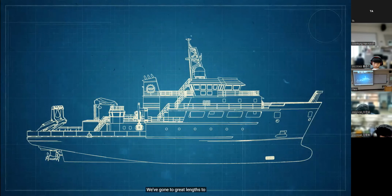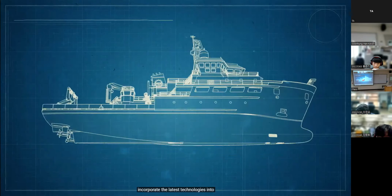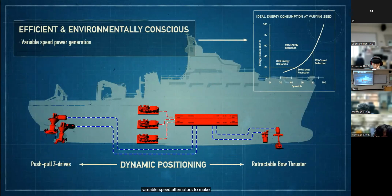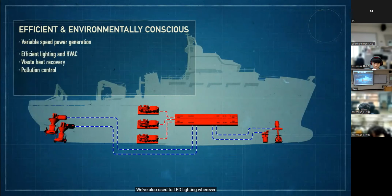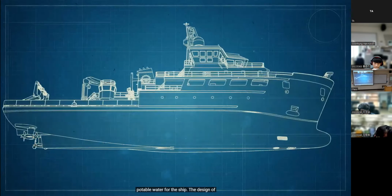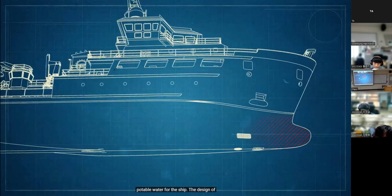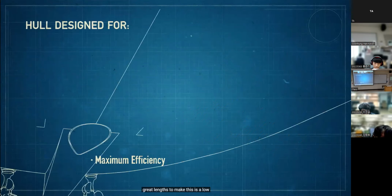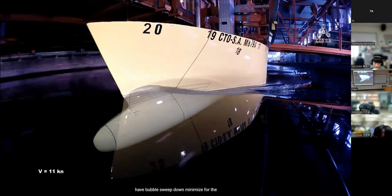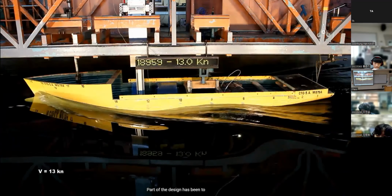When we were approached by Oregon State, one of their key objectives was to make this as green a ship as possible. We've gone to great lengths to incorporate the latest technologies into the ship to keep it as environmentally friendly as we can. We've decided to use variable speed alternators to make electricity. We've also used LED lighting wherever possible. We're using waste heat, so the heat from the engines, we'll use that to heat domestic water and to actually make potable water for the ship. The design of the ship is very important to the efficiency of the ship. And so we went to great lengths to make this as low resistance a hull as we could, in keeping with the desires of the scientists to have bubble sweep down minimized for the performance of their instrumentation.